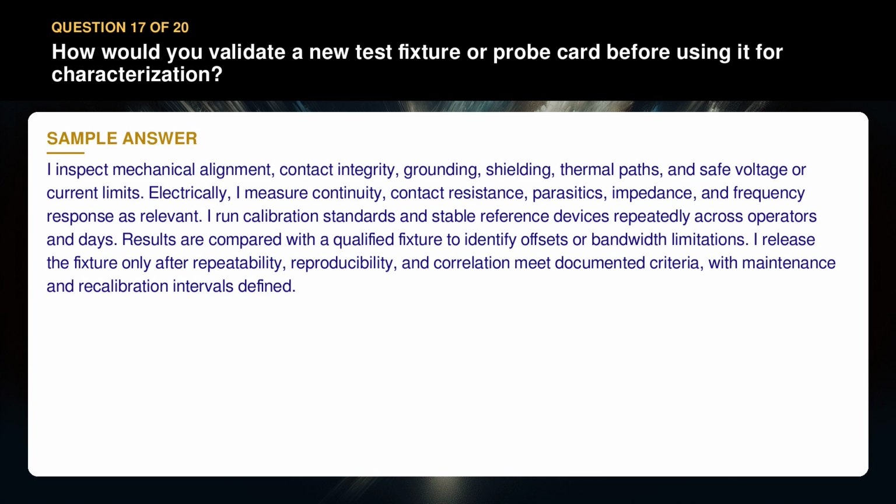I run calibration standards and stable reference devices repeatedly across operators and days. Results are compared with a qualified fixture to identify offsets or bandwidth limitations. I release the fixture only after repeatability, reproducibility, and correlation meet documented criteria, with maintenance and recalibration intervals defined.